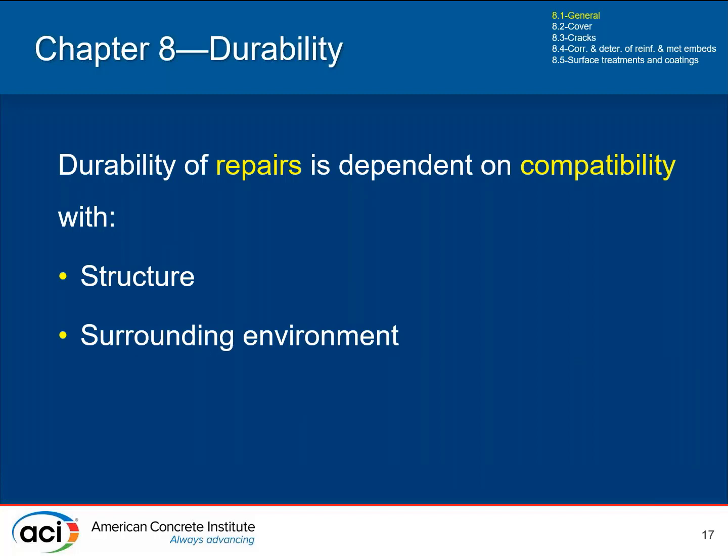But the first thing you really need to think about, the first way that durability comes about, is making sure the repairs are compatible with the structure. A lot of what I said on the first slide relates equally well to repairs and new design, where you have a new structure you're starting with. You still should think about the exposure conditions, the detailing, the materials.